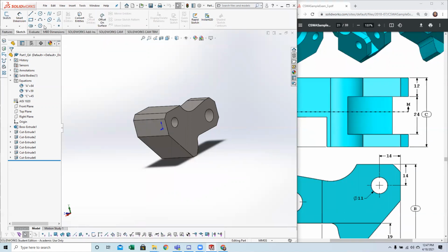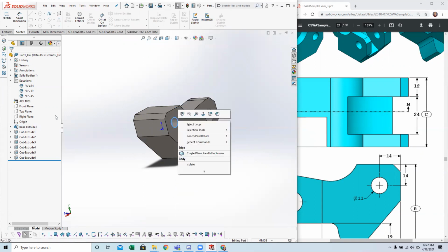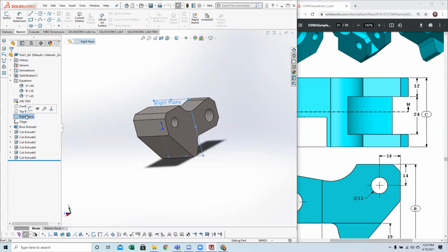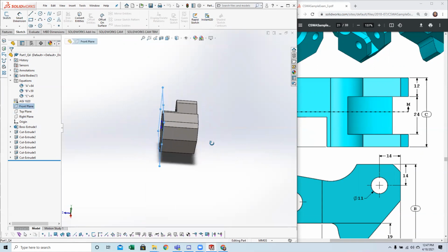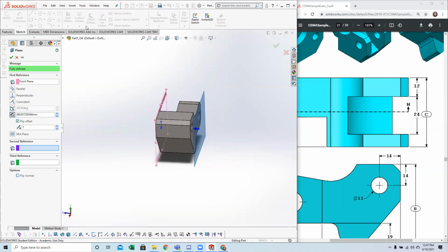I don't quite remember where it is, but another thing we can do that's actually a shortcut is we can select this plane. Let's see, which plane is this? So this is on our front plane. One thing we can do is press Control and then left click, and we can actually drag while selecting one of these corners, and it does create that reference plane for us. So there's actually no need to even go through all the menus.